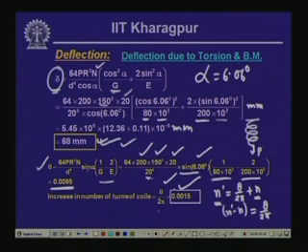So, that is the number of turns that are increased because of the axial pull P that is acting in the spring, and that is the value of n dash minus n. N is the number of turns which we had initially, and n dash is the number of turns that is getting introduced now because of the angular rotation theta, which is given by theta by twice pi.